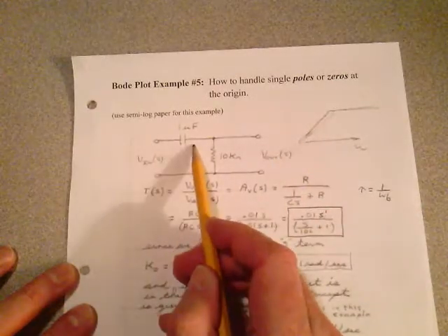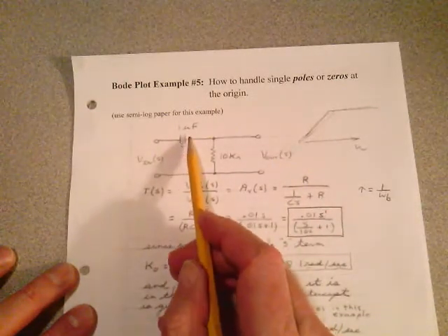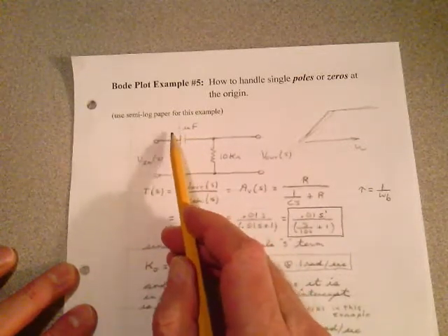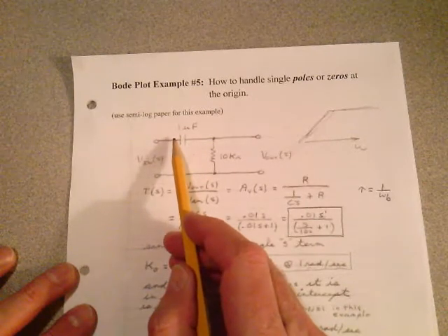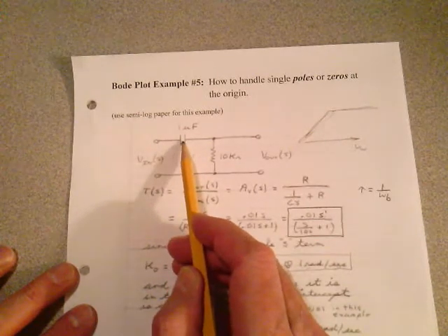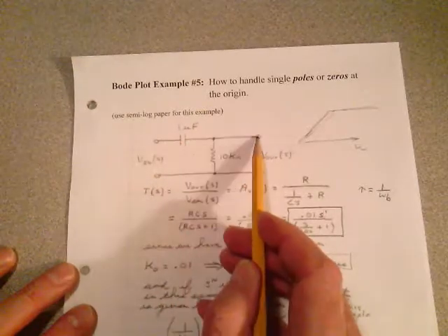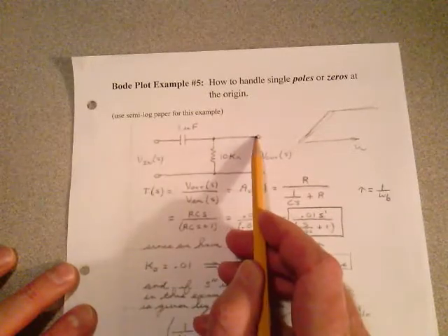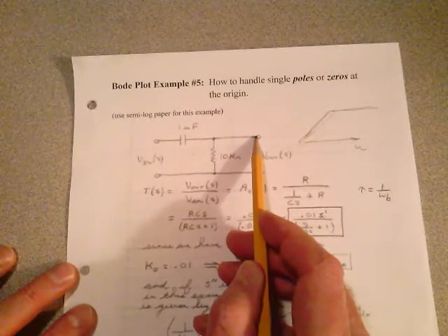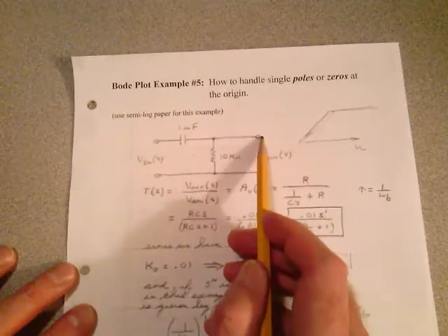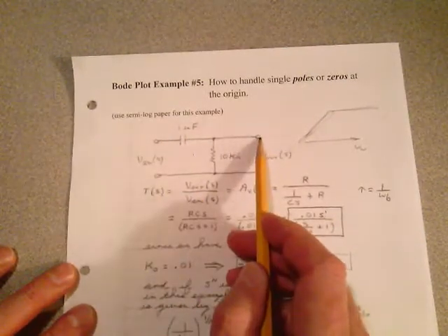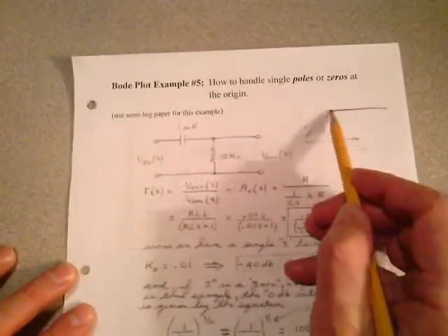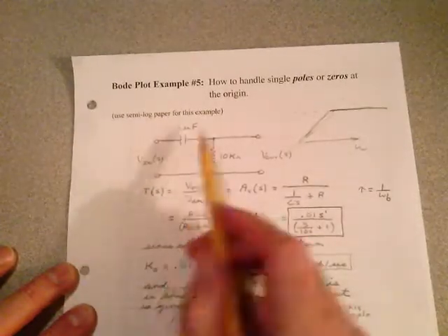At the real high frequencies, or when you get higher and higher in frequency, this looks more and more like a short because the capacitive reactance gets smaller and smaller based on the capacitive reactance equation, and it passes the signal through. It passes the signal through at 1-to-1, so it's going to be 0 dB. Don't forget, 0 dB doesn't mean you have no gain. It means you have a gain of 1. If you have 10 volts in, you get 10 volts out. If you have minus 3 volts in, you get minus 3 volts out, because that looks like a short. At the high frequencies, it looks like a short, and you can pass the signal.